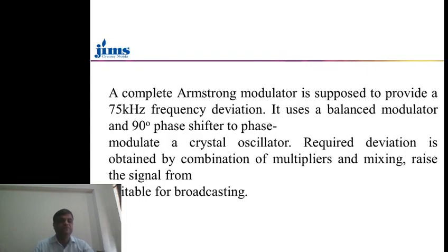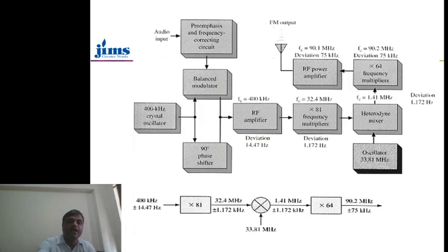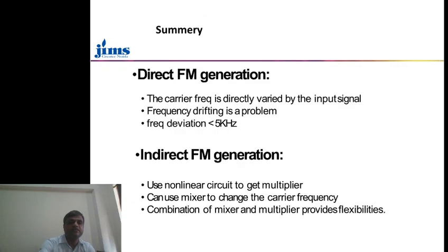And the second is, we take the samples, voice samples. It means we have a voice sample that is around 400 hertz, and we convert it to 400 kilohertz, and we convert it into 92 megahertz. It means we modulate the frequency. So that's all about the Armstrong method.